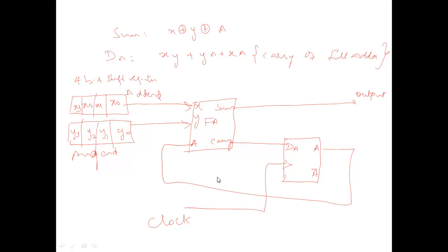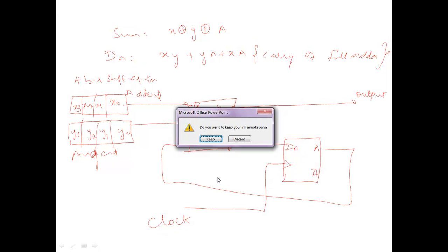When the question is for design of the serial adder, we are expecting you to draw the state diagram, explain the state diagram clearly, draw the state table, and take the K-map of the state table and implement the circuit diagram. So you can see in implementation we are simply using a full adder and one single D flip-flop with a shift register for storing the addend and augend, which completes the shift register operation. Okay, so thank you.